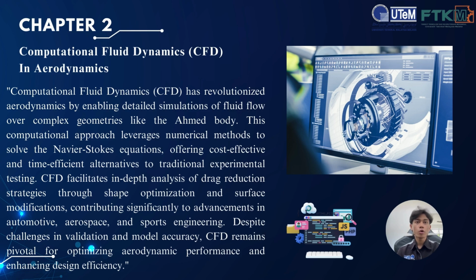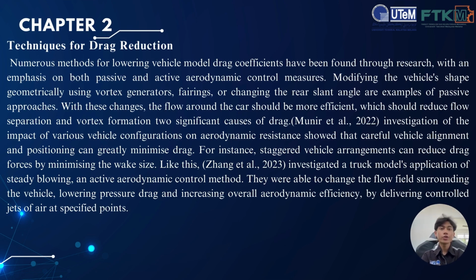This computational approach leverages numerical methods to solve the Navier-Stokes equations, offering a cost-effective and time-efficient alternative to traditional experimental testing. CFD facilitates in-depth analysis of drag reduction strategies through shape optimization and surface modification, contributing significantly to advancement in automotive, aerospace, and sports engineering. Despite challenges in validation and model accuracy, CFD remains pivotal for optimizing aerodynamic performance and enhancing design efficiency.